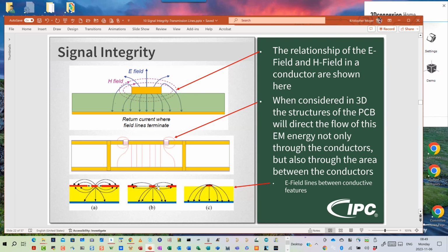They're going to want to go the shortest distance they have to go to get to a conductor in the amount of area. So the nice thing here is that because this vertical wall is very thin compared to this wide horizontal face right here, the majority of the E field lines are still going to want to come down here, but we will get some that way. And if I have no side geometry conductors of return, then all the E-field lines are going to go down this way. Again, they're going to fill in the area to make a uniform loop area right here.